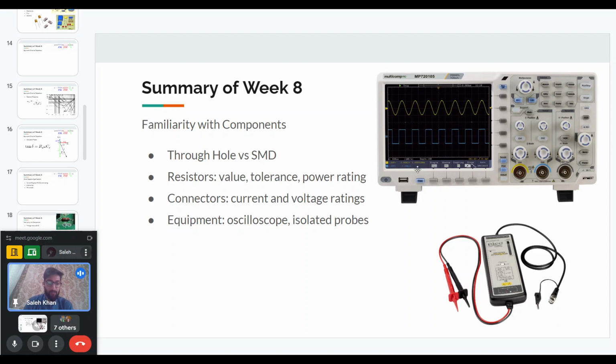And an important aspect in power converters is that when we are measuring different voltages, these oscilloscopes usually have different channels to measure different voltages simultaneously. But usually these multiple channels have the same ground. Internally, the ground of each of these three channels is connected to the same point.